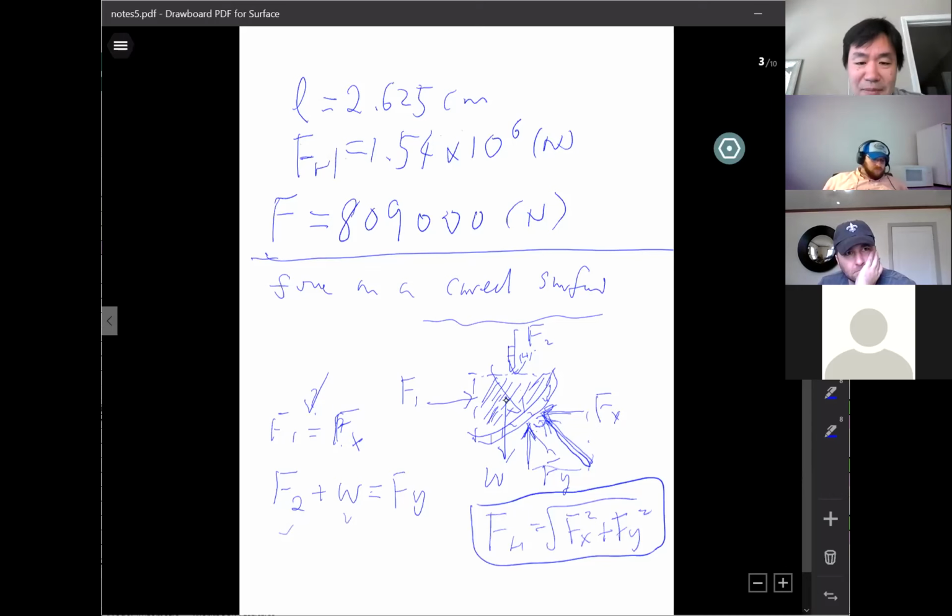Right, this is the fundamental, very general case: an arbitrary surface underwater. So it's a curved surface. We basically don't need the integration. We cut it into two planes, a vertical plane and a horizontal plane. Separately find the force on the vertical plane and the horizontal plane. Then find the weight of the fluid within these two planes. So that's the procedure. It could still be tedious, but there's a way to do it. You don't have to do integration.